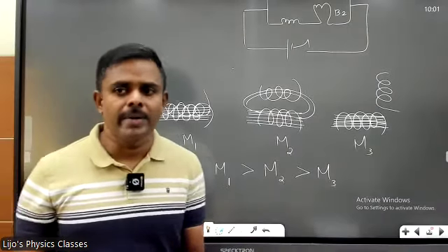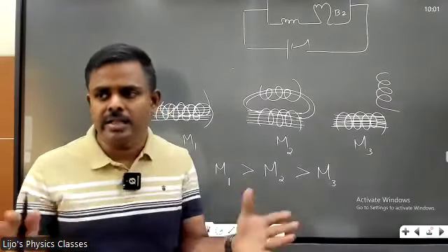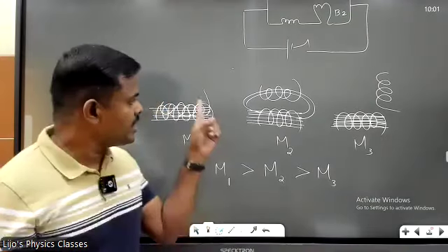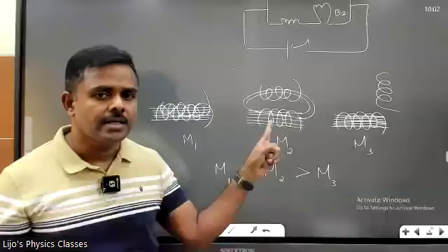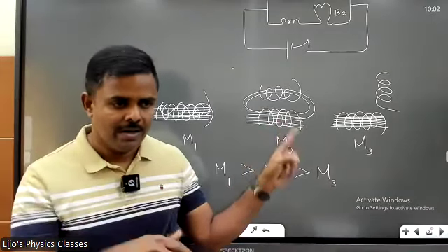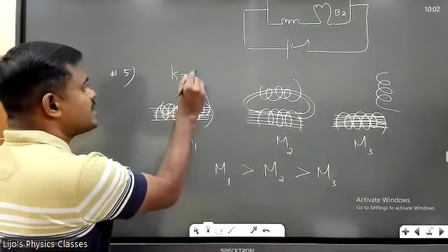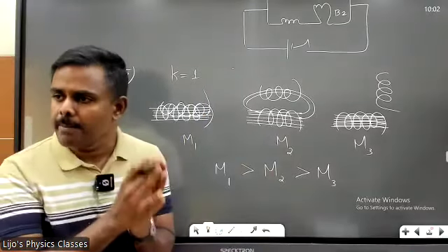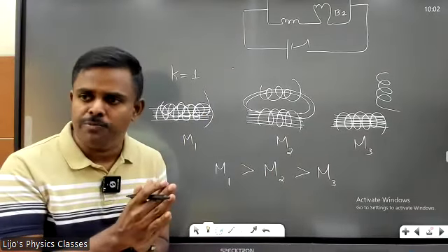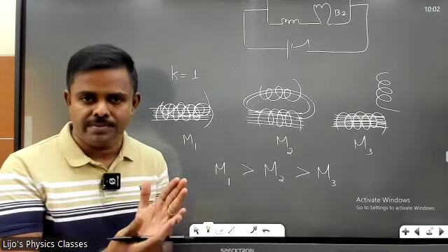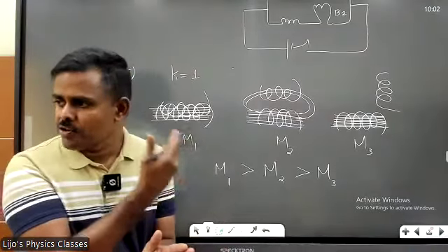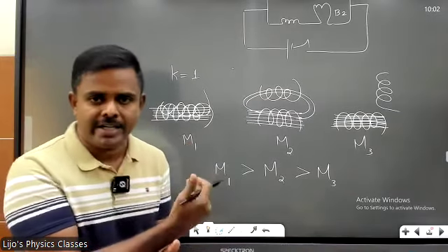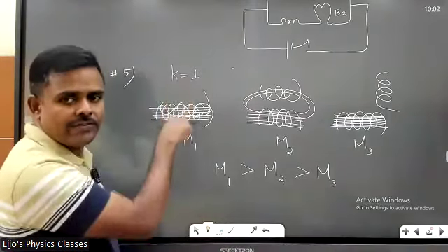There is a term called coupling coefficient which tells you about it, but that is deleted now. Coupling coefficient here is 1. Coupling coefficient here is 0. Coupling coefficient here is in between 0 and 1. Coupling coefficient 1 means 100% coupled. Entire flux of primary moves to secondary. Coaxial winding, entire flux of primary gets transferred to secondary. That is called coupling coefficient 1.